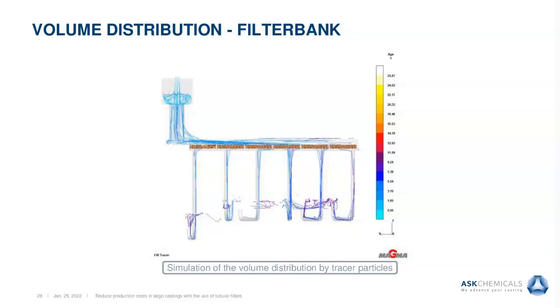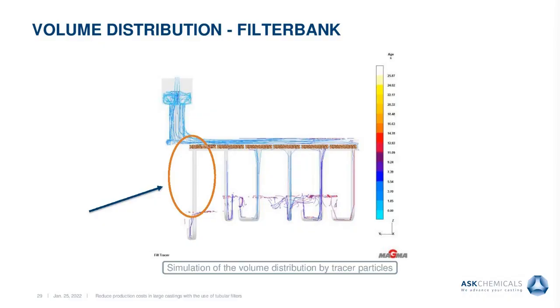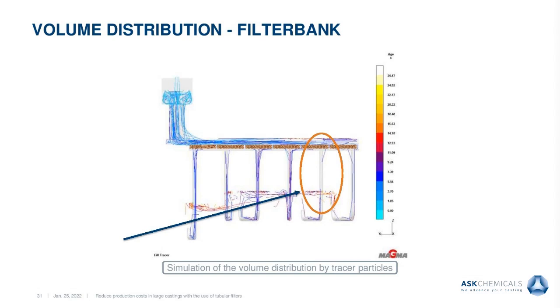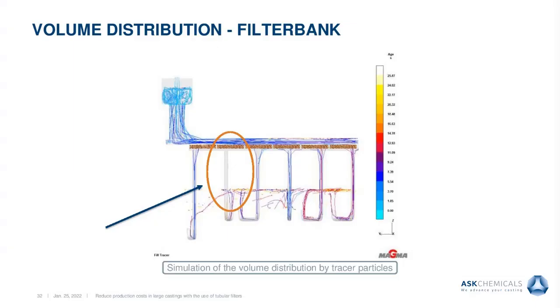But that is really very, very important to know. When you use single filters side by side in a bank, you really increase the risk of filter breakages. And that is absolutely not to be underestimated. Very, very important in my opinion. That is the reason that I want to show you these simulation pictures here.